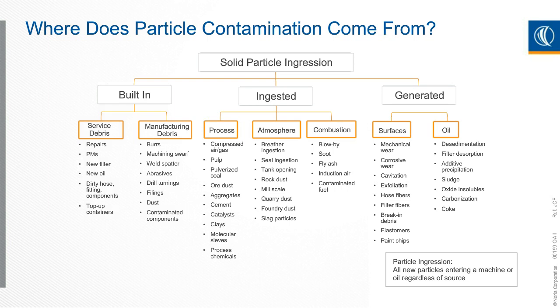Whatever it is, that's when we're going to lead towards a more detailed oil analysis approach to figure out through elemental analysis or other forms of analysis to figure out exactly where that particle might have come from.